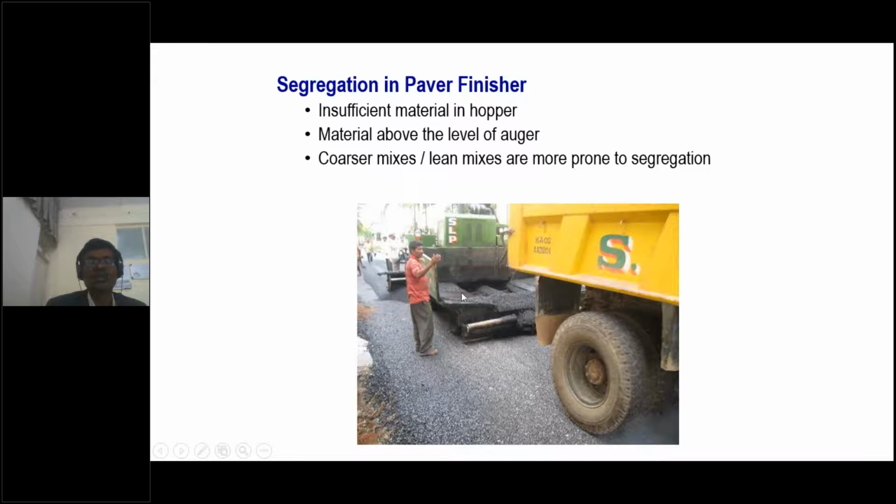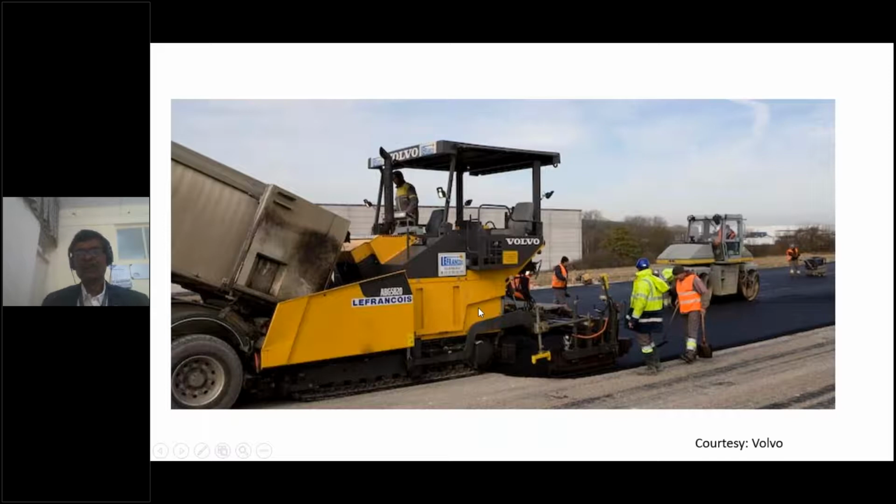I was also telling, the paver should never be stopped, whether it is a concrete paver or, in this case, a bituminous paver, ideally speaking, unless it is very, very essential. So that is one care we need to take. No mix should be left in the hopper, right?